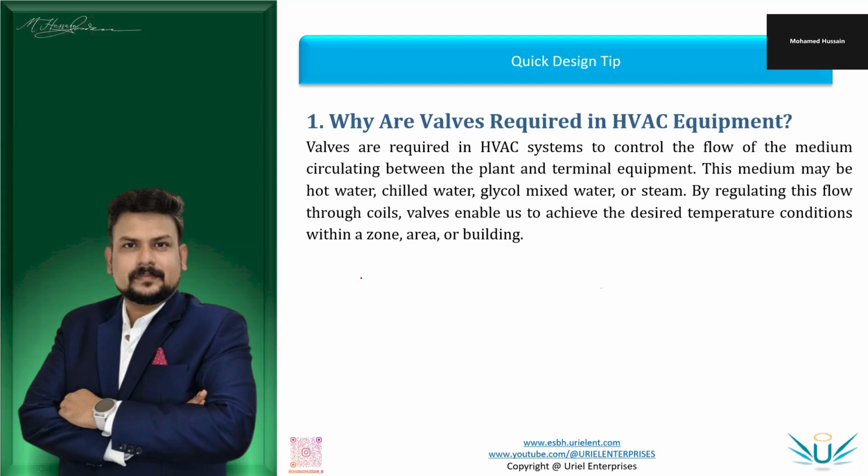See, first you have to understand that the AHU works based on the number of zones that are actively occupied. What is the demand? Based on the demand, the AHU fan speed ramps up and ramps down, and accordingly the VAVs are serving.